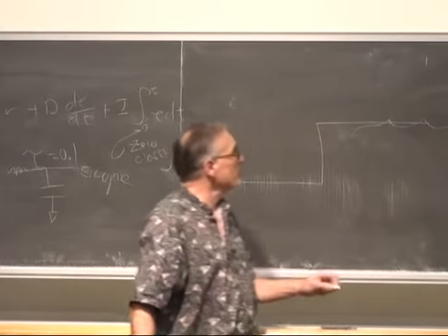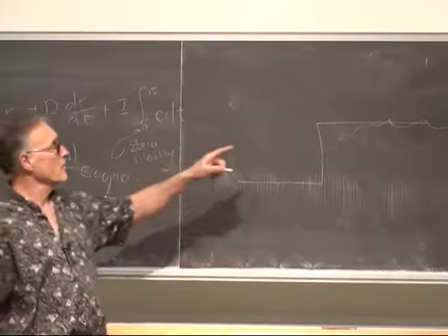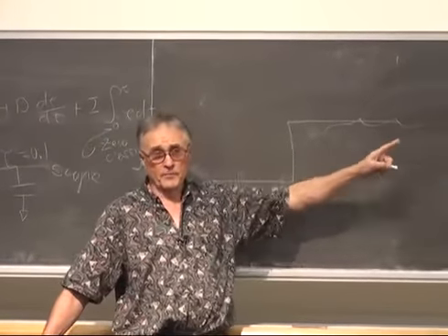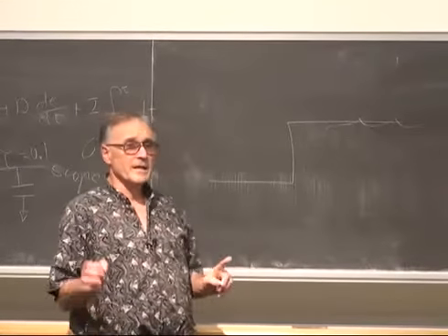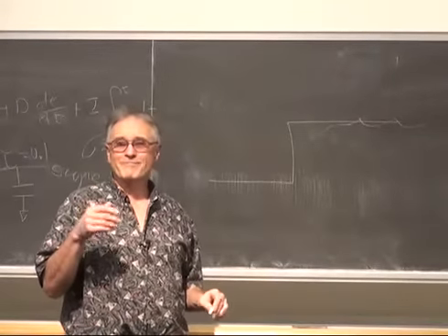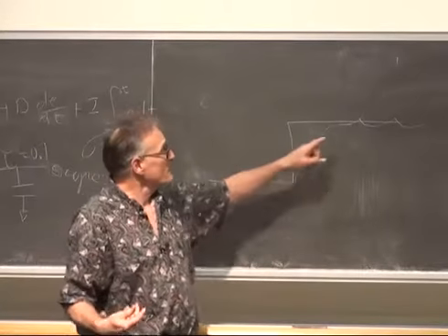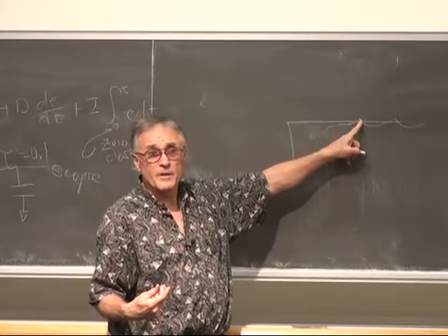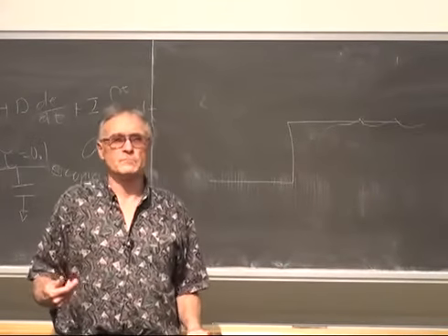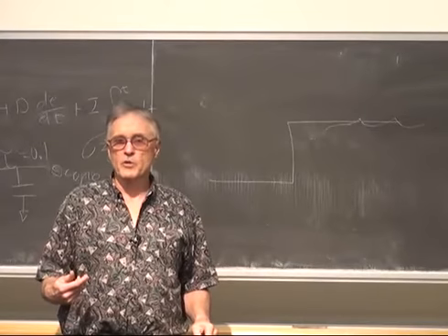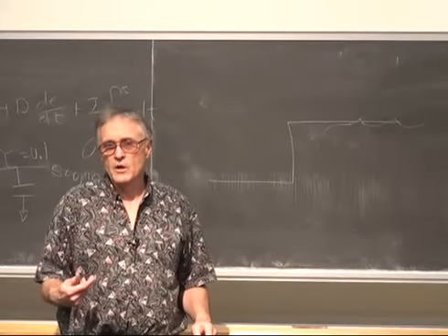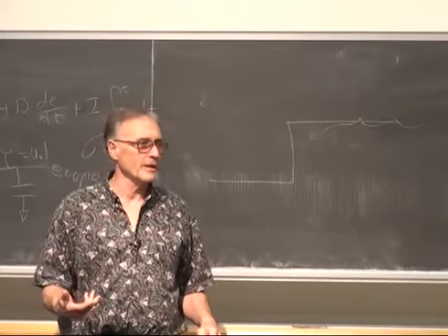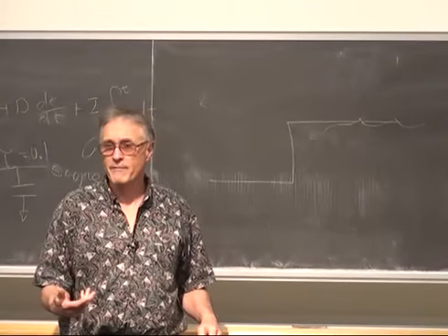And so if you reset the integral term to 0, you're going to get a scalloping effect like this forever. If you reset to the value the system had on the step before it overshot, it'll be about right. So you might reset to 0.9 of the current integral or so, something like that, 0.8, 0.9, 0.95.